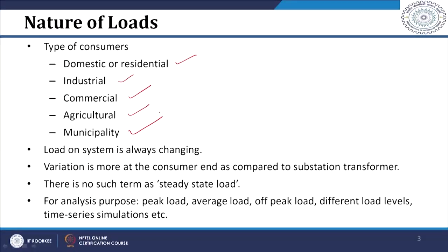And if you observe, the peak demand of these consumers may come at different times. If you observe domestic consumers, the peak demand generally comes in the evening. However, the peak demands of industrial consumers may come at day times, and there is a possibility that there are two peaks in the industrial consumer load curve. Then the municipality kind of consumers generally operate at off-peak hours because these are nothing but pumping and lighting loads.